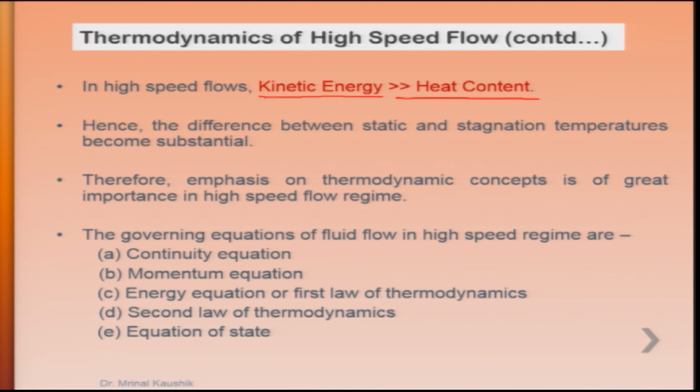In turn, in the high speed flow regime, the final governing equations which deal with high speed flow are continuity, momentum, and the energy equation, which is also termed the first law of thermodynamics, the second law of thermodynamics for the direction in which the process is carried out, as well as the equation of state for a perfect gas. We can say P equals rho R T should be taken into account in the analysis.